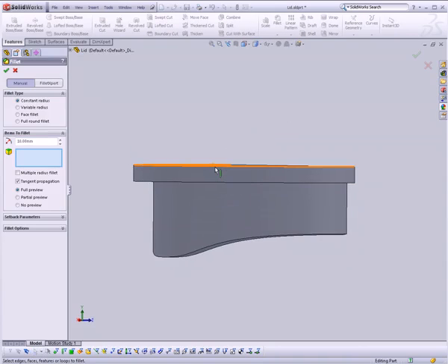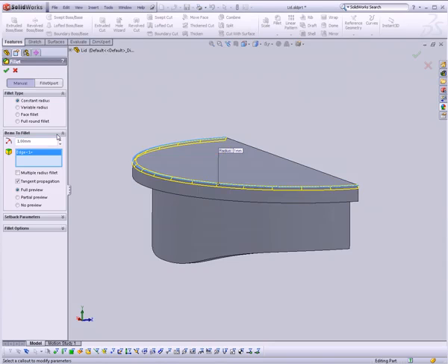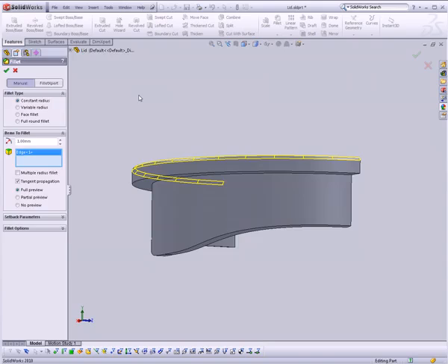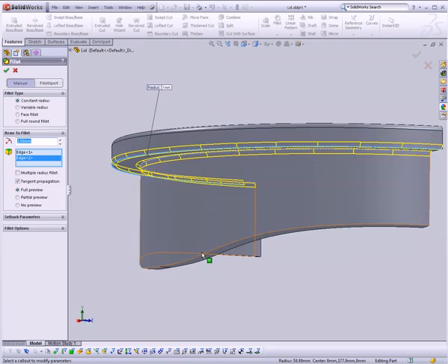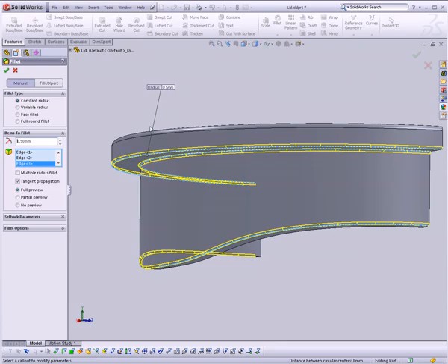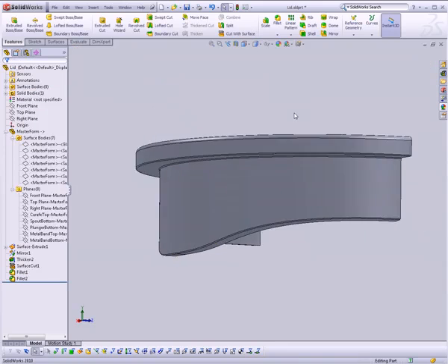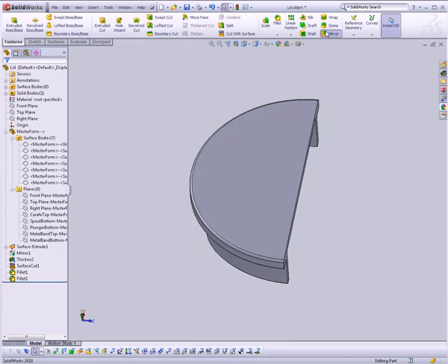Let's go ahead and add a couple of little fillets, like maybe that looks like a 1 millimeter fillet on the top. And I'll add some minor radii on these other edges. Just go ahead and give those like a 0.5 millimeter, even a 1/4 millimeter, because they're pretty sharp. And we can go ahead and mirror this part across now.